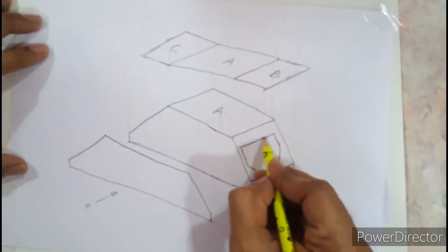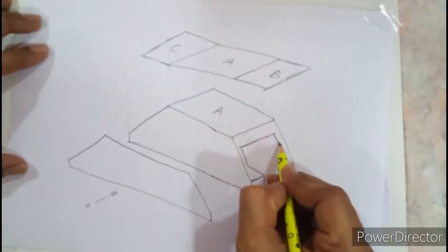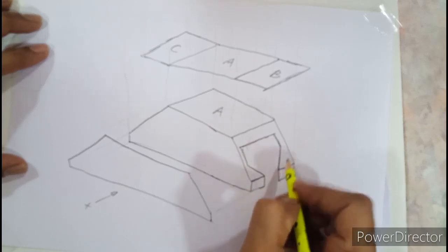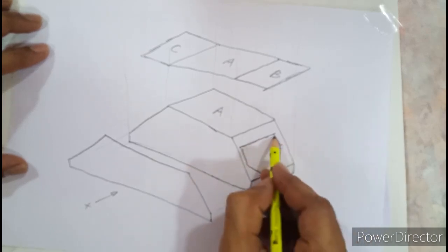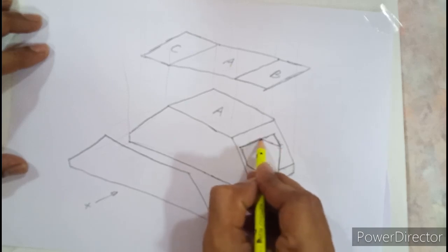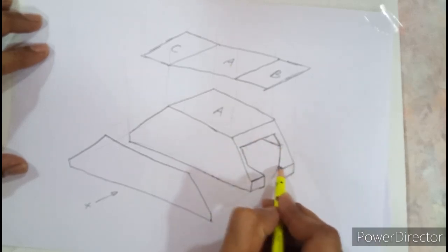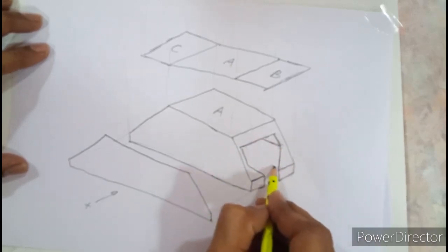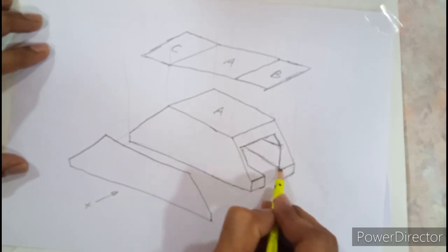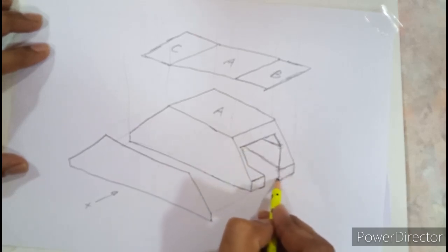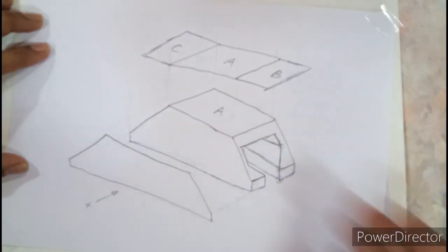and you know that in engineering graphics or in any object, whenever there is a change of surface, an edge has to be there. So you can look here, two lines are meeting, so one edge has to go inside, the third edge. From here, three lines are meeting, so one edge has to go inside. From this corner there are two edges, the third has to go inside. So there is an edge going inside.